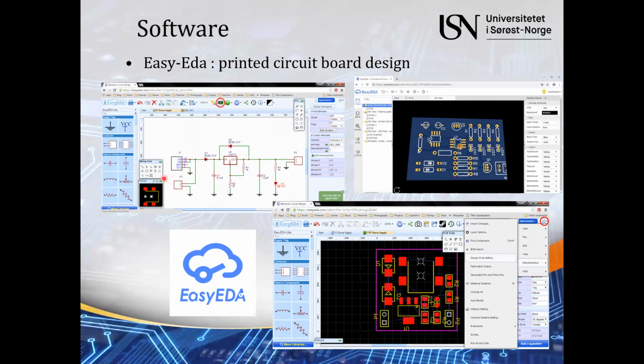So in the software, you will see that the first step is drawing the schematic of the circuit with the symbols of the components. Then a simple button in the software will generate this kind of view here. Then you just need to connect the components to each other, as suggested here by the lines created by EasyEDA. And once you connect them all, you can have a 3D view given by the software, and you can see how the final PCB should look.